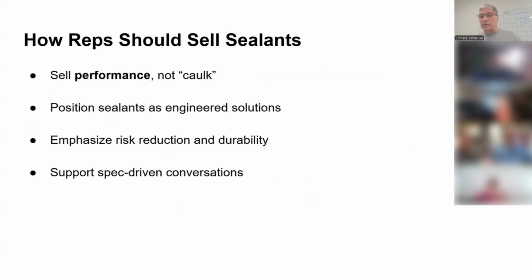We want to know the data sheets really well, and the ASTM C920 is going to tell us a lot of what we want to know as far as single component, what type of materials it's good for, classifications for expansion and contraction. And then some of the other stuff too, of course, your shear strength, the elongation we're always promoting because we have such good elongation with NS and SL.